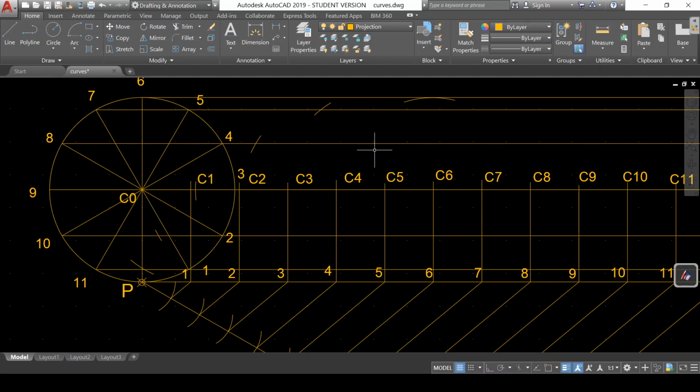Gradually it is going to climb like this, and then it will come on the right side of this center line. So C7, C7, 28, and now don't cut on this side, because P has reached the top and then it will slide down on the right side. It will roll on the right side of this center line. So 28 here on the right side on the locus of 7. This is the locus of 7, this line.